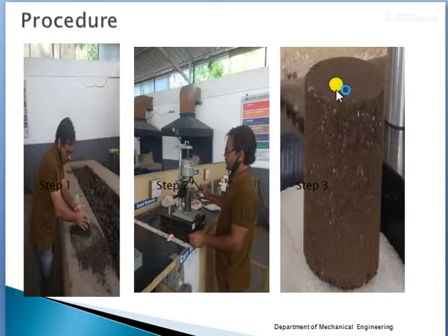We are going to prepare this sand specimen dimension with the help of the sand rammer. First we mix the required sand, then put it in this specimen tube, and ram it using the rammer to get a specimen of 50 by 50 mm. The strength is governed by the amount of bonding material. These are the initial steps to make the sand specimen.